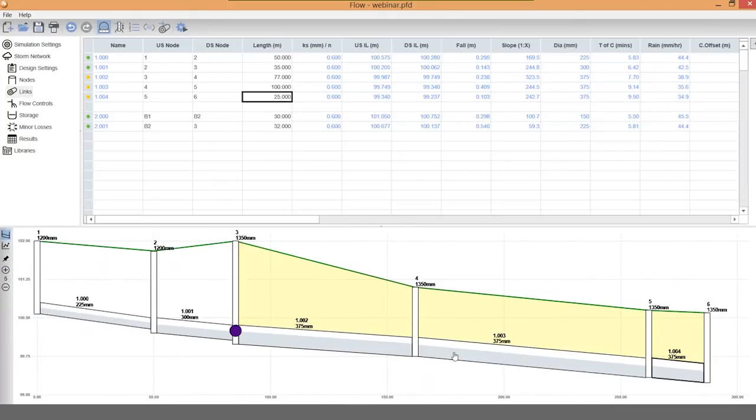The shaded blue area in the pipes is our proportional depth of water, so this is what we're actually designing to. And the yellow shaded area represents those pipes where we haven't managed to get our 1.2 meters cover all the way along the length yet.